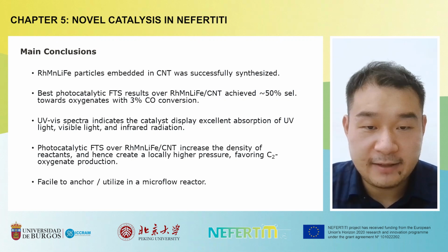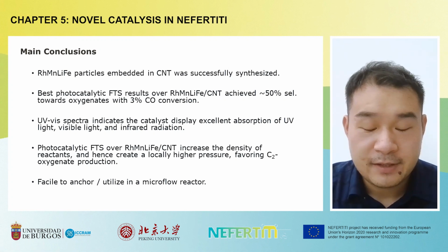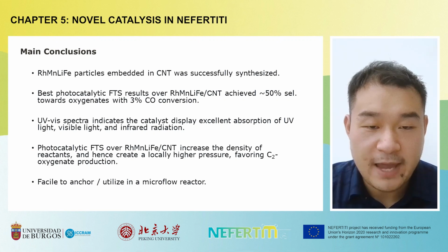The photocatalytic Fischer-Tropsch over the promoted rhodium-based catalyst can increase the density of reactants and hence create a locally higher pressure favoring C2 oxygenate production. And last but not least, we found this type of catalyst is facile to anchor, and that provides us the opportunity to utilize it in a microflow reactor.